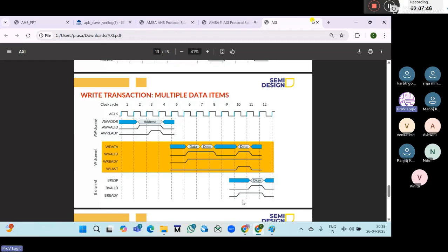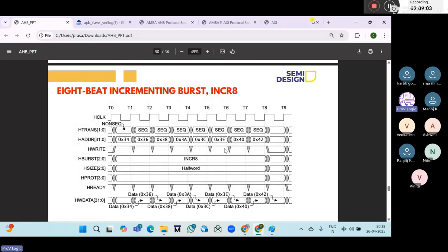Non-alignment is nothing but the data address not perfectly matching with the data boundaries. That's why in the AXI protocol a non-aligned address is allowed for the transfer. In AHB, that is the limitation we have, because of alignment we don't have flexibility in the data transfer with respect to these addresses. In aligned transfers, the width is fixed. Within the width only we need to transfer, whether it's 32-bit data or 4-bit, 8-bit data, the width is fixed.